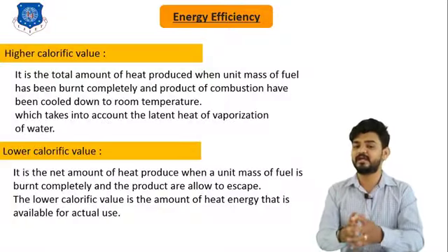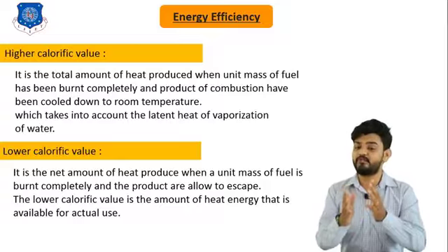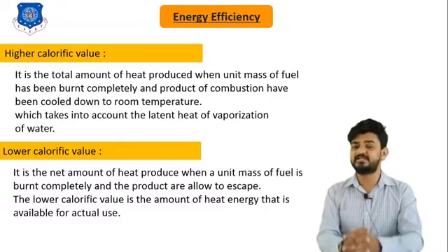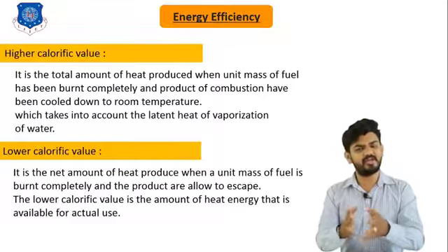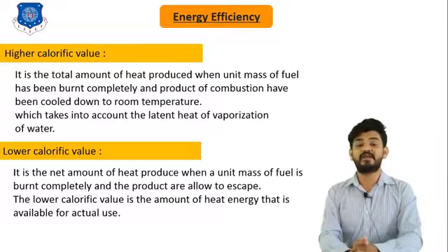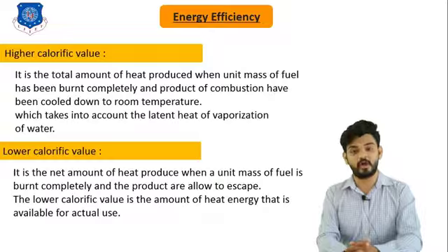But from here you can read it on the screen. The products of combustion have been cooled to room temperature. So when the products of any combustion reaction are cooled to room temperature, their energy is known as the higher calorific value. This higher calorific value or gross calorific value is the calorific value which accounts for the latent heat of vaporization of water.